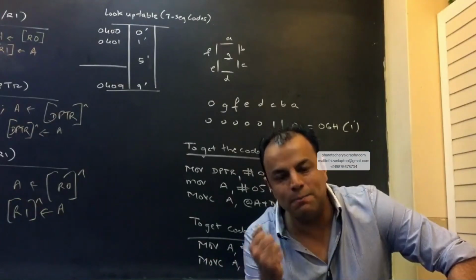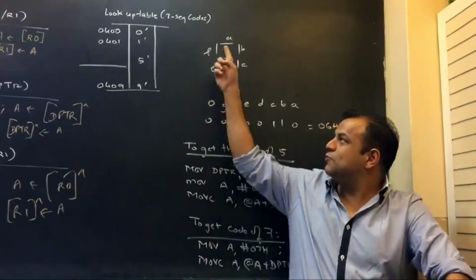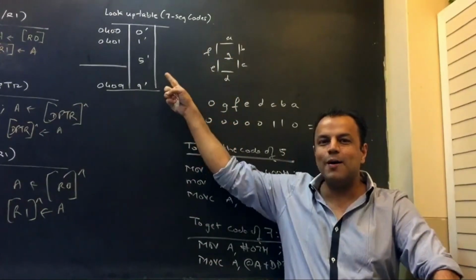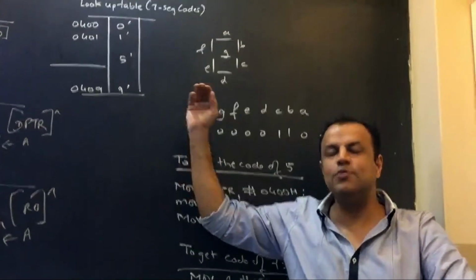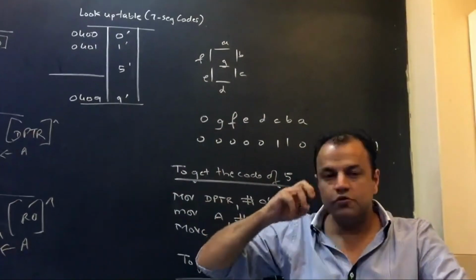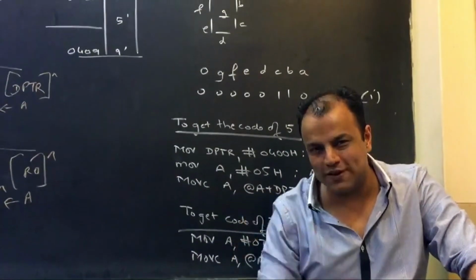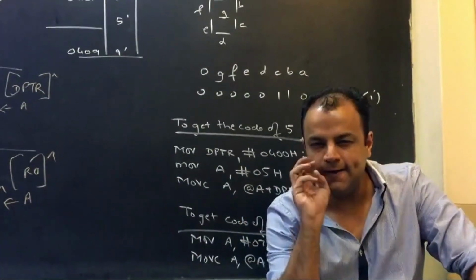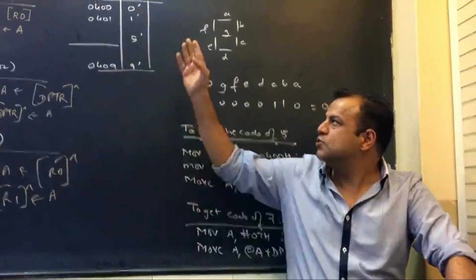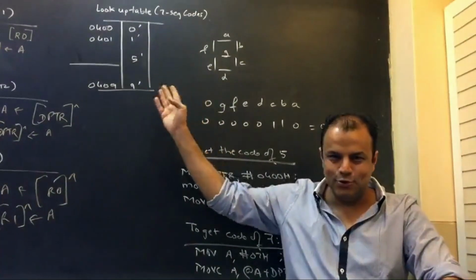Permanent data is always stored in the form of a lookup table. Okay, you'll know what it is. Okay, just tell me. So this index addressing mode that we are learning, where address is given as a sum of 2 registers, is an ideally created addressing mode suitable for accessing a lookup table.